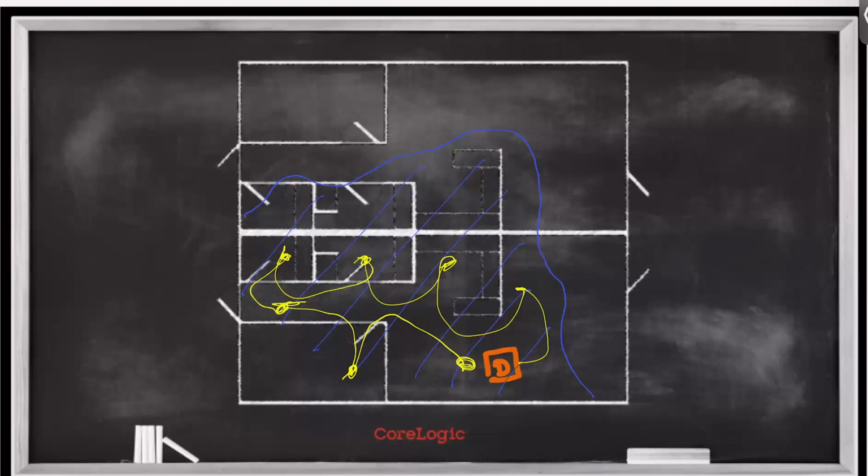The problem we run into is that we have this barrier, this common wall between what is likely two different apartment units or condominiums, and there's likely no opening, no entrance, and no ability to pass air through that wall into the neighboring space, unless there was damage that caused me to open that wall, right? So if the water source was inside that wall in the kitchen area, and we had damaged materials inside that wall, and we opened that common wall, then it would be potentially possible for me to establish airflow and communication between these two spaces.